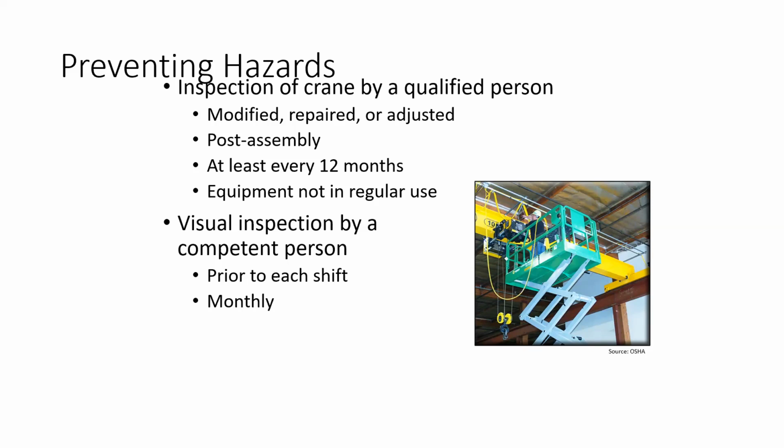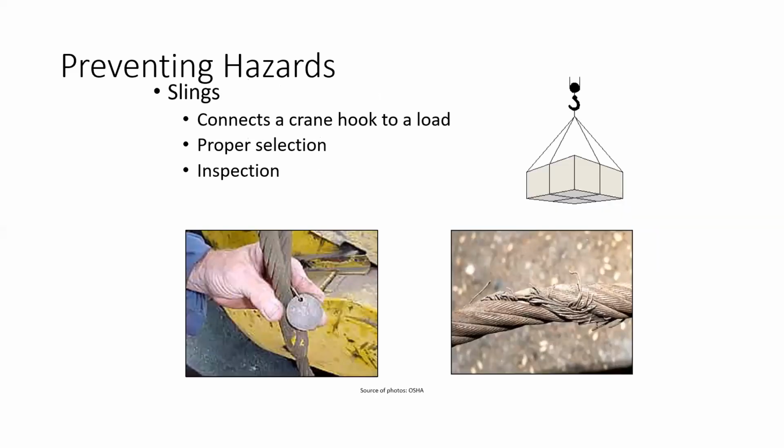Okay, and the crane should be inspected by a qualified person every 12 months for preventive maintenance, or maybe for corrective maintenance if the equipment is not in regular use, or after assembly, modification, repair or adjustment. Okay, this is the inspection for cranes.